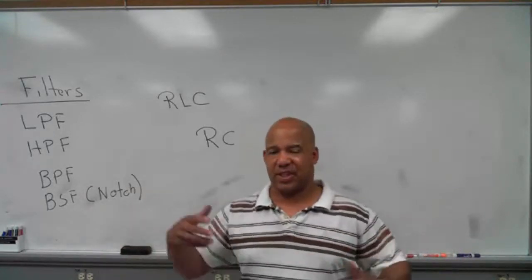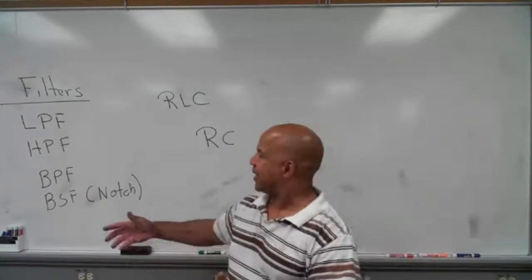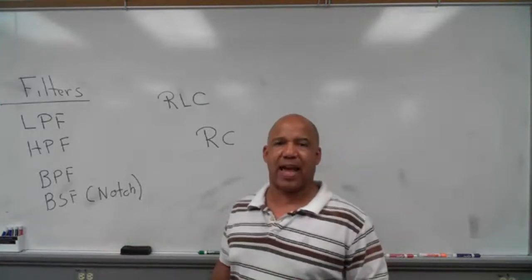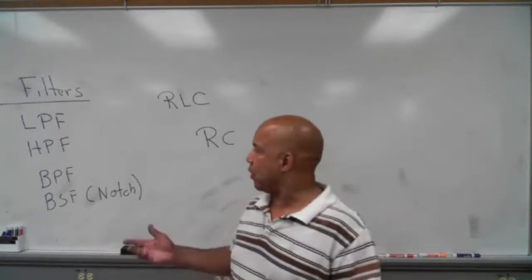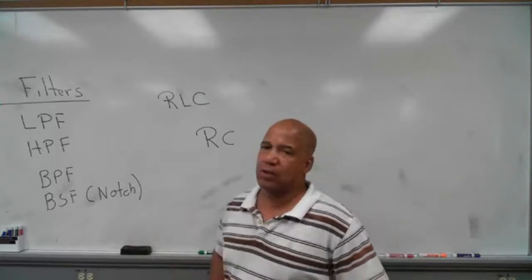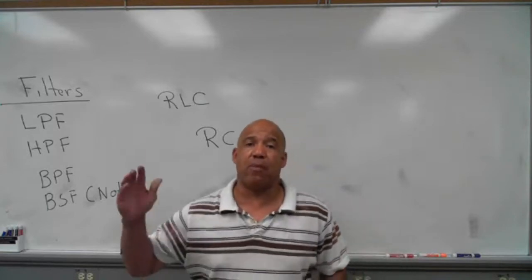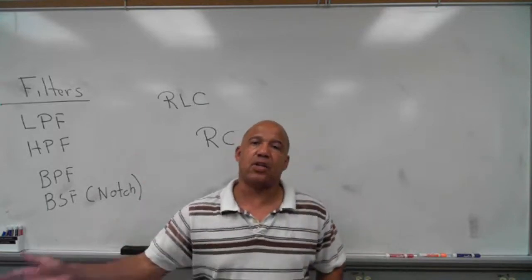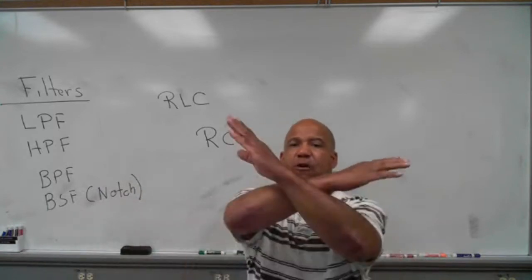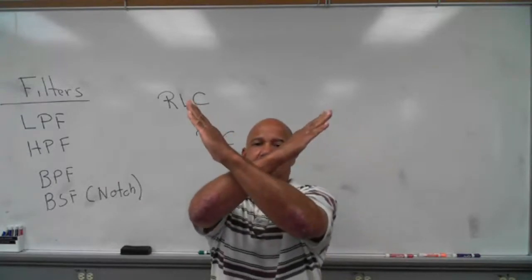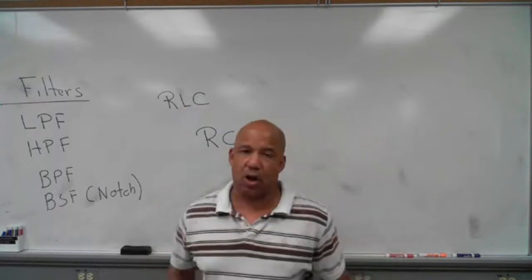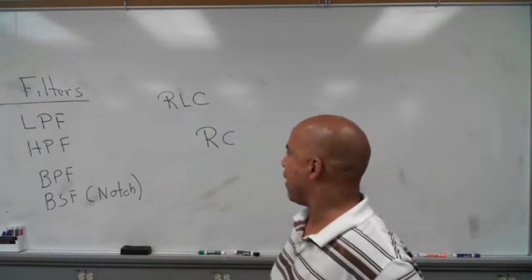And we just kind of thought through it to see, well, how would we connect things up? What kind of filters would I need to get an audio system to work and have what you might call high fidelity? So we worked through that. And in that, we learned how to put those graphs together. And we learned a new term, the crossover point. When you move from one part of the frequency range to another, from one speaker to another, you want one to pick up where the other leaves off. And so they cross over at that point. And the graphs actually make that crossover. So the term crossover point, if you're familiar with audio, that's where the term is derived. That's where it comes from, the actual graph.